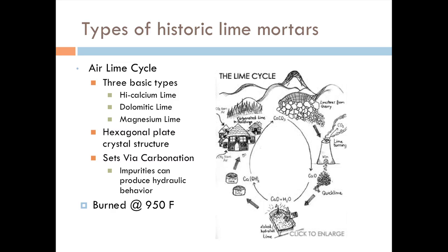And from there, we would end up adding sand to it. Sometimes they would take this quicklime and add sand and water to it simultaneously, and you would see that method in building, primarily for stonework, sometimes brickwork.